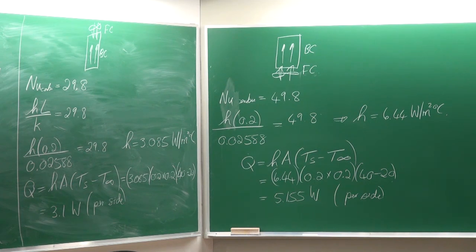So for that reason, over the years, they've tried many solutions for it. Firstly, fins, then fins with fans, and at this stage, they are looking at condensation and evaporation on the outside so that you can get heat transfer coefficients of orders of magnitude of 10,000 and more, because then you can get all the heat out. But it means that when you start using these complicated systems, then you start using fans and pumps, and the reliability of those are issues. So it is an industry in which a lot of work is being conducted at the moment. However, the challenge still remains. You need to get 60 watts out of 1 square centimeter. Well, not only 60 watts, 100, 120 watts, and even more out of 1 square centimeter. That is the huge challenge at this stage.